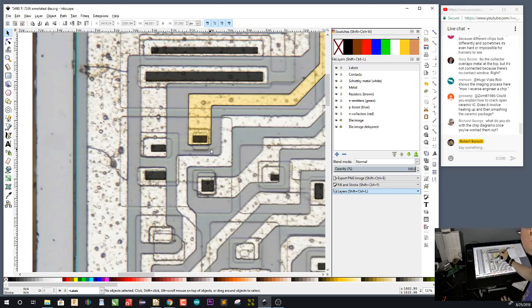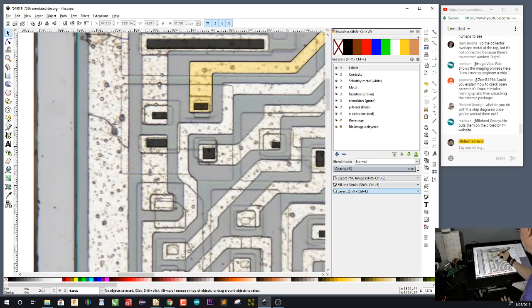And the reason that you see this other square is that typically, in order to get really, really good contact between an N-type semiconductor and metal, you put an additional strongly doped N region, called an N plus region, in order to get a lot better contact. So I suspect that's what we're seeing here. Probably the same thing over here.